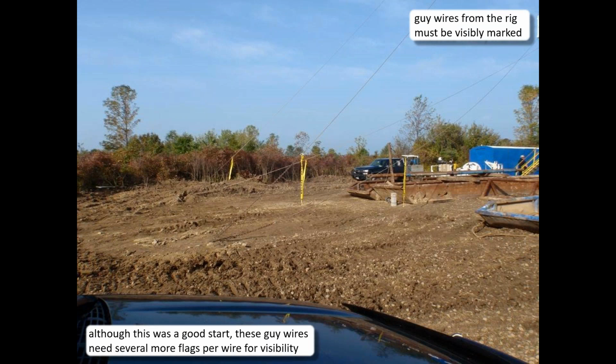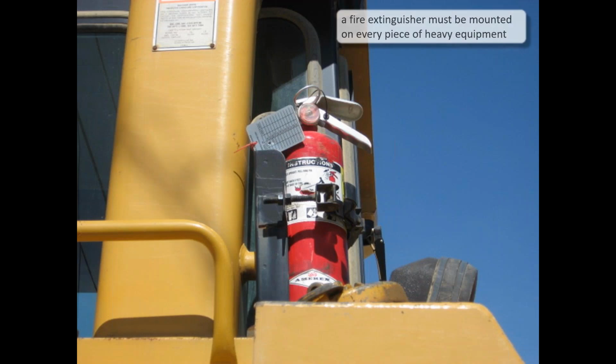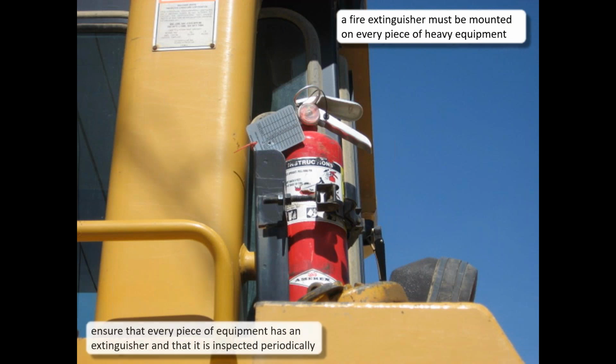And once again, not too many of us are dealing with these, so I'm not going to spend too much time on it. But you are required to have a fire extinguisher on every single piece of heavy equipment, and it has to be inspected annually at a minimum. We should be inspecting them monthly, but every single piece of heavy equipment has to have a fire extinguisher on it.